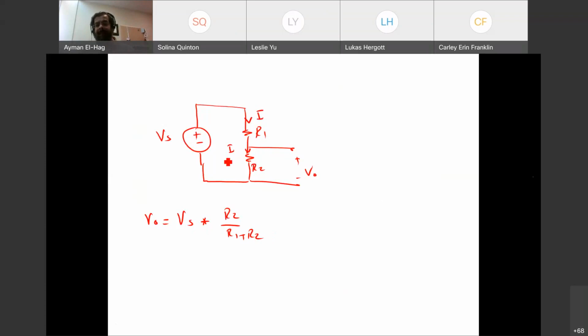Now, imagine I am bringing my voltmeter to do the measurement. So I'm bringing here a device to measure. We connect two leads between these two terminals to see how much the output voltage is. Now, once we connect a circuit, there will be a current here. So as a matter of fact, this current will not be the same as this current. Why? Because we have a current going on. This is why for this measurement system, I want the input impedance to be very, very, very high. Ideally it is infinity, so that the current that goes here is equal to zero.